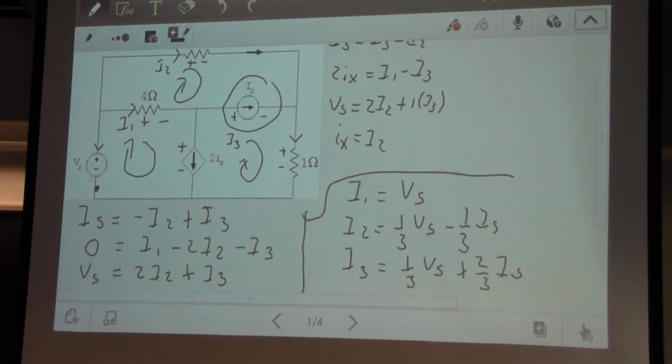But what it says is basically, because there's no mixing between Vs and Is in this term, I could potentially just forget that there's a current source, so get rid of this term, for example. Just solve for that system with only a voltage source, and obtain a solution which is going to be this term that I just left there. And then afterwards, I'm going to get rid of the voltage source and think that there's just one current source, and then I don't get this term, I only get the other term. But you already have the other one, then I add them together.